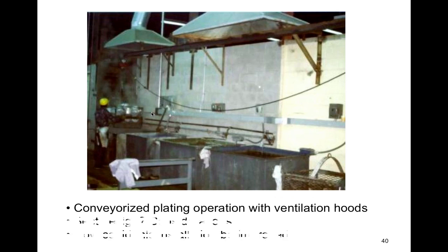Okay, here's a system of vats here, a plating operation. Now usually these vats are heated, right? So what's going to happen is that warm air is going to rise. So they have the hoods up above it. Now, if you're a worker and you're leaning over, that ain't helping you very much because it's pulling it right past you. And those hoods are so far up, they're probably not very effective anyway.